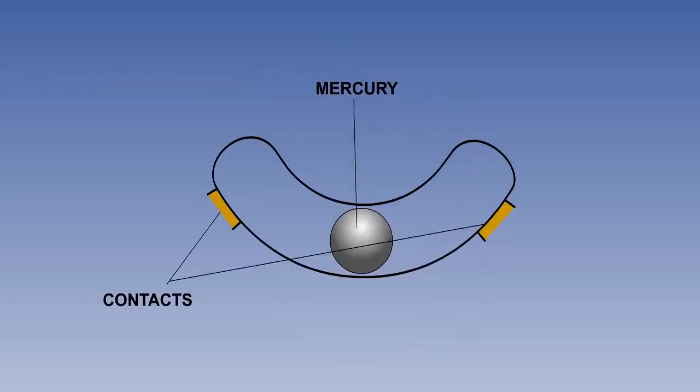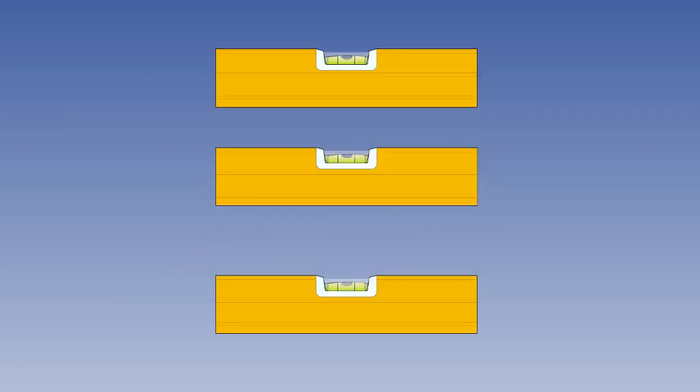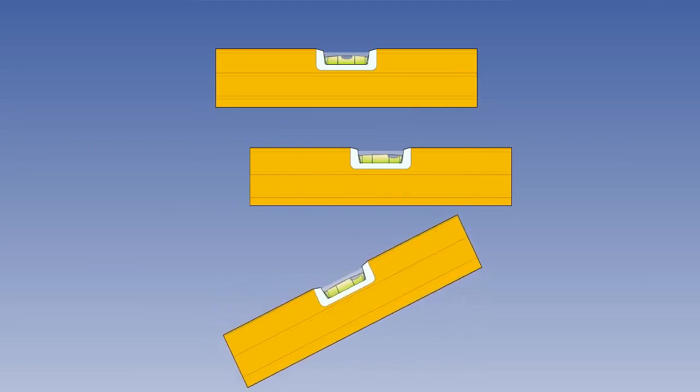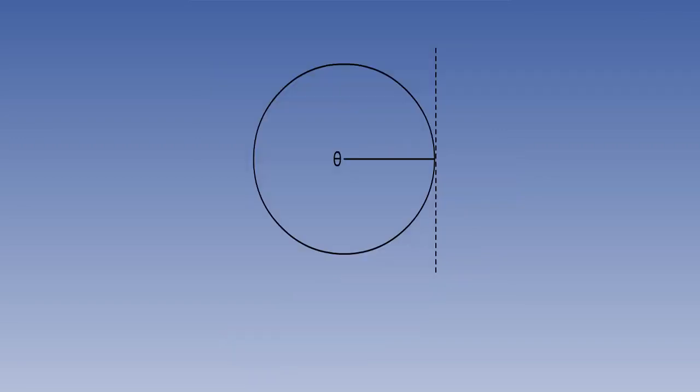The traditional way of keeping gyros and instruments level is by using gravity, for instance, by using mercury gravity switches. But as we've pointed out before, the accelerometers themselves would be the best choice for gravity sensors. However, they are being used for sensing horizontal acceleration. Like the spirit level, you can't use the same device to give you both gravity and accelerations. It's one or the other. So we continue to use the accelerometers to measure horizontal accelerations, and we have to find another way to keep the platform at right angles to the gravity vector.